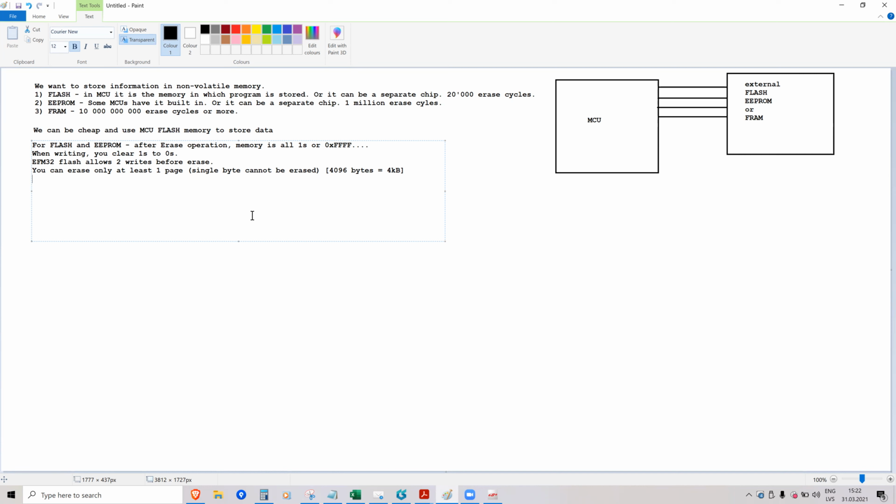So when you organize the memory, if you are using, for example, some file allocation library, sometimes they require that you tell them the page size so that the software can manage it and take into account that one block is 4 kilobytes, and then when it reaches the end of one block, it can erase it and then use it again, and so on. Sometimes you just have to tell it in the settings.